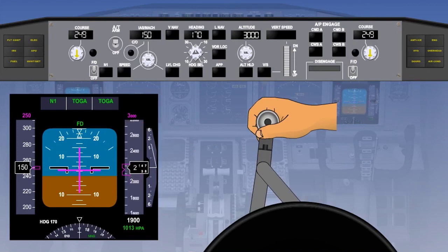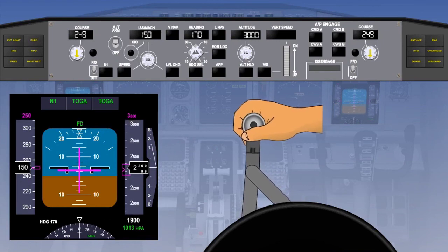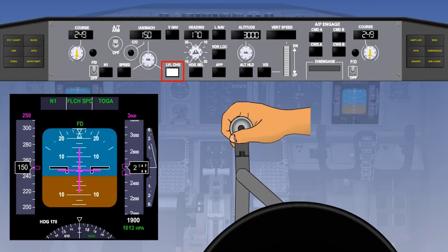After reaching reduced go-around thrust, pressing either take-off go-around switch the second time signals the auto throttle to advance thrust to the full go-around N1 limit. After reaching reduced or full go-around thrust, the auto throttle go-around mode can be terminated by selecting another automatic flight director system pitch mode, or when altitude acquire enunciates engaged.